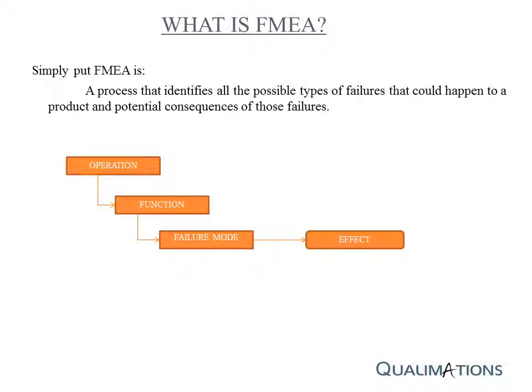Each failure mode is now derived by studying the ways of failure, but with several operations it is likely to see hundreds of failure modes that are possible. This, when multiplied by the number of causes, would exponentially grow the possibilities of fixes. In order to get more focus, FMEA uses a risk ranking process, which is a numerical conversion of the impact, the frequency of occurring and the current set of controls.